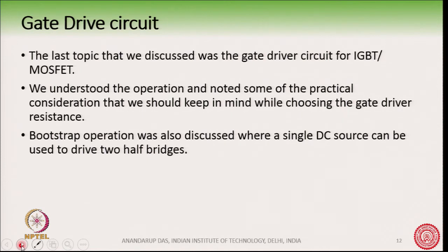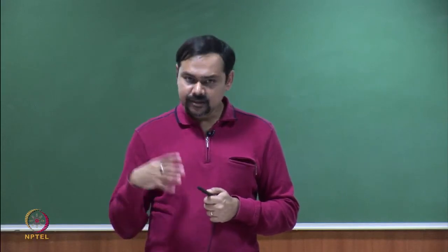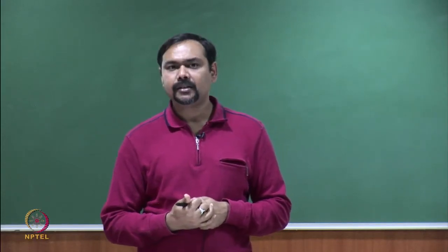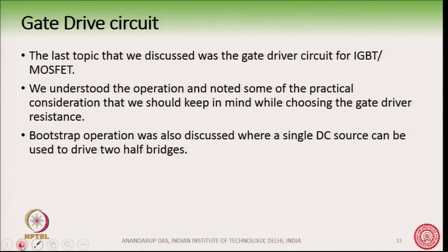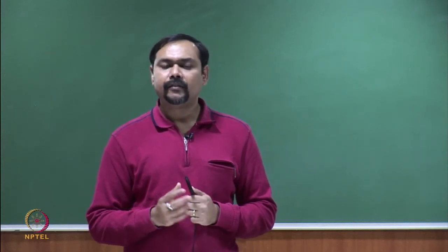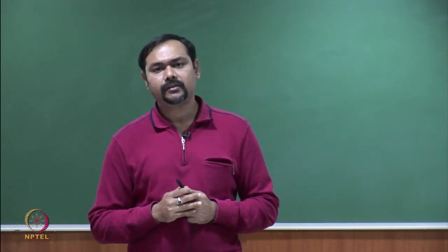We understood some of the operations, like how the IGBT is turning on, what is the sequence of events happening while it is turning on and while it is turning off. Based on this understanding, we can choose the components, and one of the most important components is the gate resistance of the IGBT or MOSFET, and there are several consequences we must keep in mind while choosing the gate driver resistance.